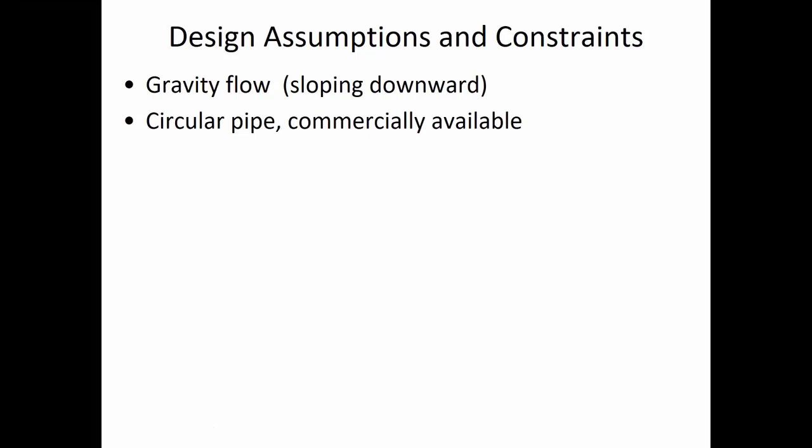In the mountains, yeah. And they must have some of the lowest costs ever, because not only was the water delivered from the mountains to the treatment plant by gravity flow, and then from the treatment plant into the city by gravity flow, but they also had enough slope to the lake that was nearby that the wastewater is gravity flow as well. Even some of the wastewater treatment used just the static water pressure to drive it. They have trickling filters where the water is spraying in a big circular tank, and they didn't have to use electricity to get it out onto the rock media.